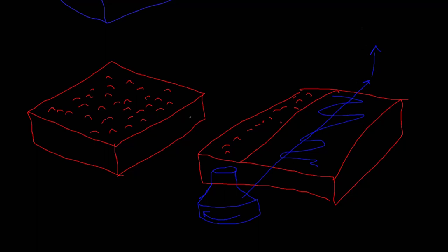So that is one of the main purposes of the face mill. You're trying to face the top of the part, make it very flat, and you're trying to do it very quickly as well, so in 1 or 2 passes. I've seen these things range all the way up maybe to 8 inches in diameter, maybe even more.